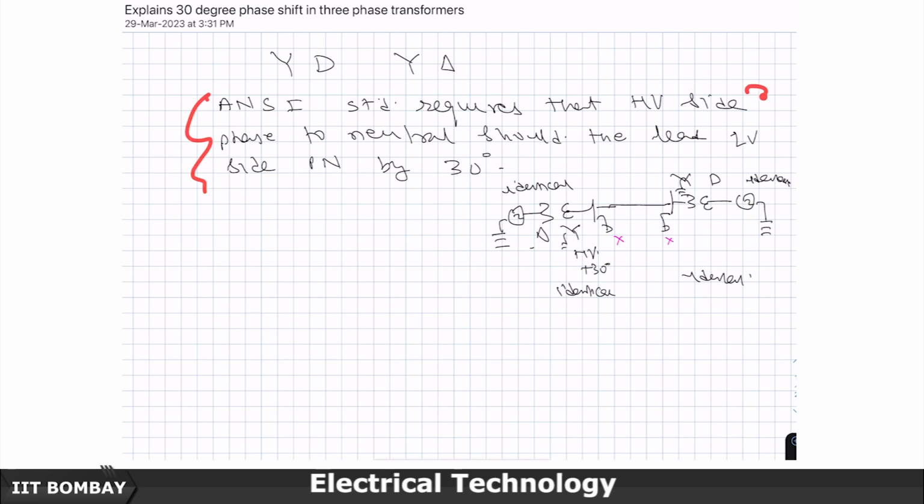So, what will happen is, if you just follow this system, a person, let us say in Shillong, is doing a transformer connection, and somebody, let us say, is doing a transformer connection in Chennai, thousands of kilometers apart, and the grid is a meshed interconnected system, and everybody is following this convention, then you are sure that there will not be any circulating currents in the system. So, this is the advantage of standardization.